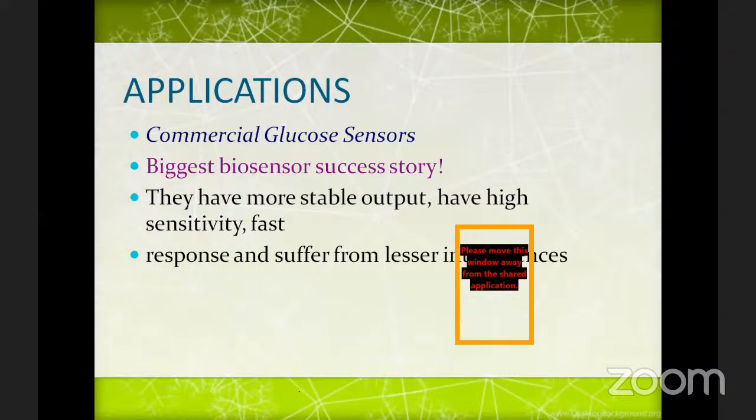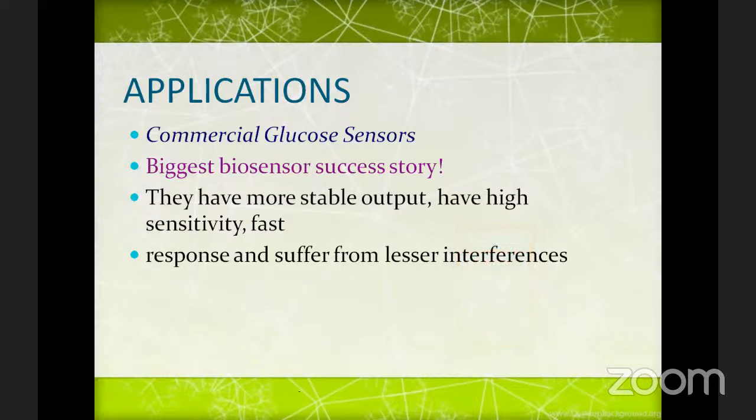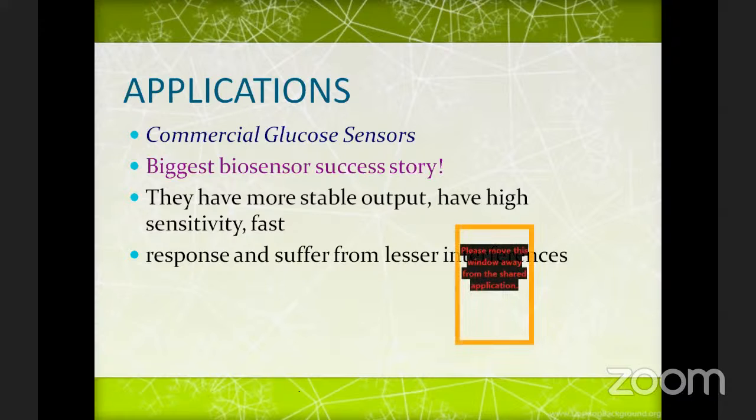They employ a thin strip of material which has a biologically active substance coated on it. When a blood sample is placed on the electrode, it creates a biochemical reaction and produces electron flow, which can be measured using the transducer. That is then amplified, and suitable signal processing techniques are applied to convert it into blood glucose units. So this is the working of a glucose sensor.